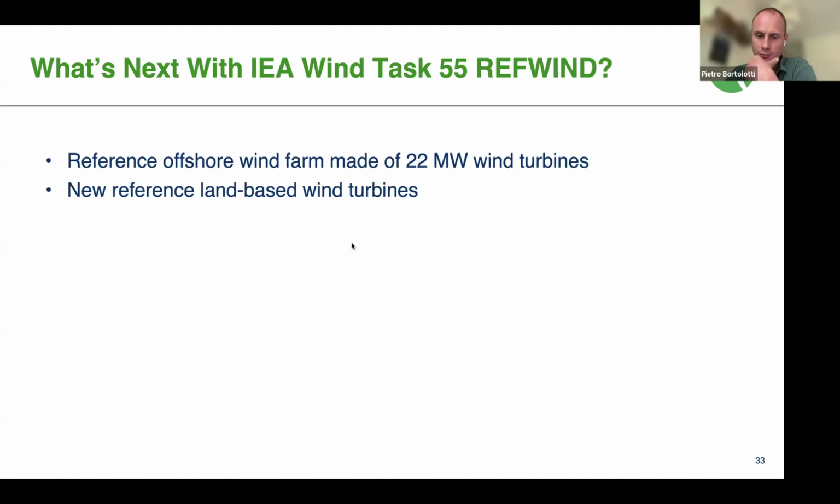Will, one question for you. Did you compare the coupled structural frequencies of the tower and the floater across different codes? So certainly for the fixed bottom case, yeah, we've had a look at that. We looked at the uncoupled tower frequencies and did a comparison, and we've also done comparisons of the turbine coupled frequencies. In the paper, the coupled frequencies are compared with a rigid tower, so we could focus on the rotor modes. But we have also done some tests with the tower flexibility included. That's not presented in the paper.